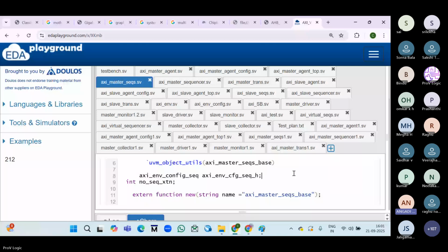By using instantiation. A DUT instantiation, that's what we call an interface. In SystemVerilog it is the same concept, but a somewhat more complex interface. In UVM also it is somewhat complex, and we call it a virtual interface. Interconnect is at the SoC level, where all subsystems will be connected on one bus. That's what interconnect is.